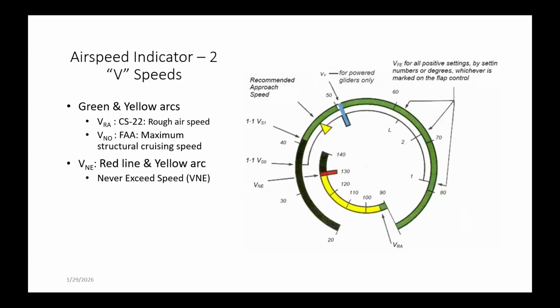In the U.S., a red line is based on the service ceiling, so that's an altitude adjusted to standard conditions, and the gross number for it is that's the altitude adjusted for standard conditions in which the rate of climb drops to 100 feet per minute. So it's real easy to say what the service ceiling is for a 172. But what's the service ceiling for a Schweizer 134? No, I'm not going there.